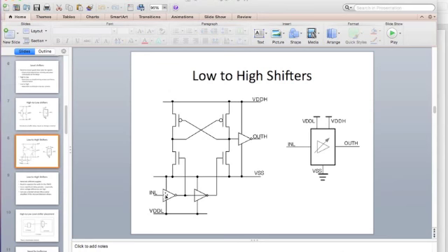So the input comes and you generate the input and its complement. So you might, for example, do away with one inverter. You don't need both the inverters. You might just take one inverter and drive it out here, and then take its complement. I mean, you have the signal connected directly here and its complement. You just need the signal and the complement. So here they have provided an additional level of buffering.